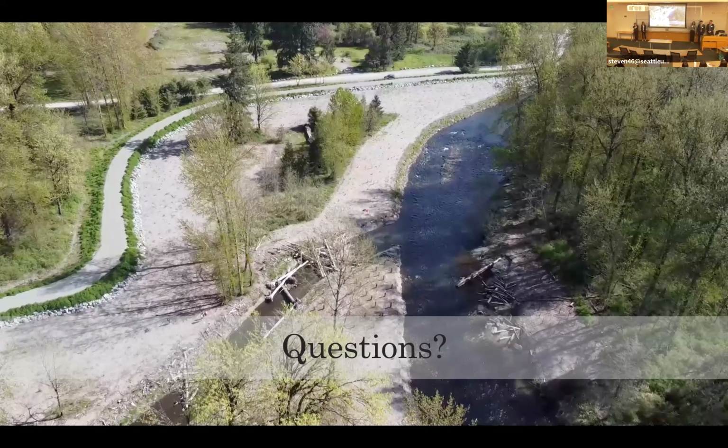As for the model, you can do it site-wide very quickly. And there's a lot of literature out there that does define what Froude number would be best for which types. But as for the field delineations, models aren't always accurate. And so maybe being able to be there in the field is going to be really good to get something that is more accurate. And same with the drone as well. There's a drawback with the drone. You can't really tell depth very well. So there's a pro and con with everything, but it really comes down to what do you have the time to do and is that model accurate enough?